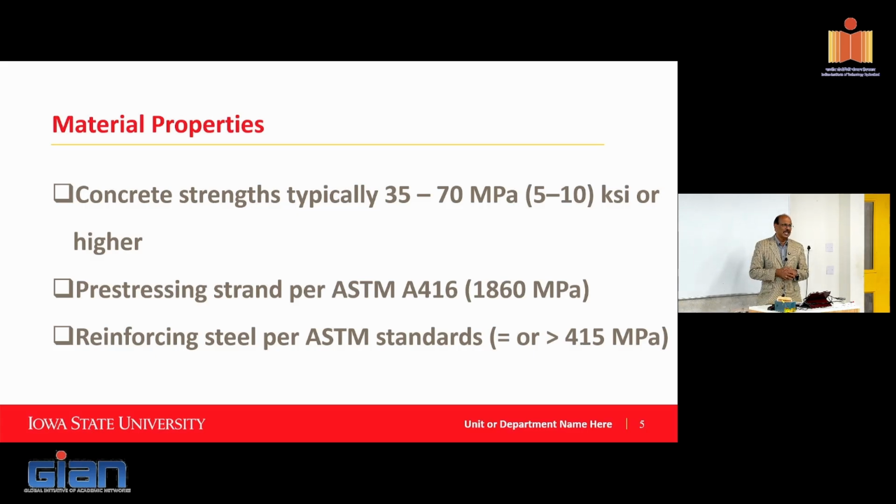Pre-stressing strand is heavily used either for pre-tensioning purposes, or sometimes pre-tensioning is done to improve construction. So if they figured that you have a long span beam that during transportation may see tensile stresses and could potentially crack, they could include some temporary pre-stressing into it, which they can cut later on. So they do creative things like that too. It's not a big challenging operation to make sure.